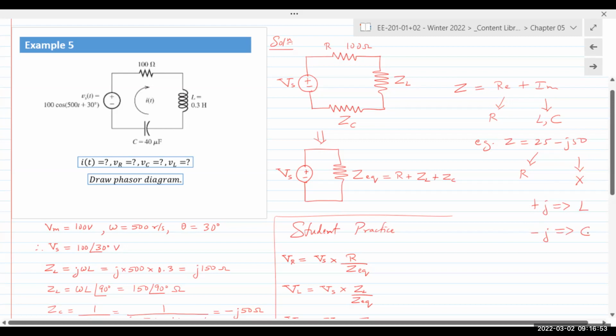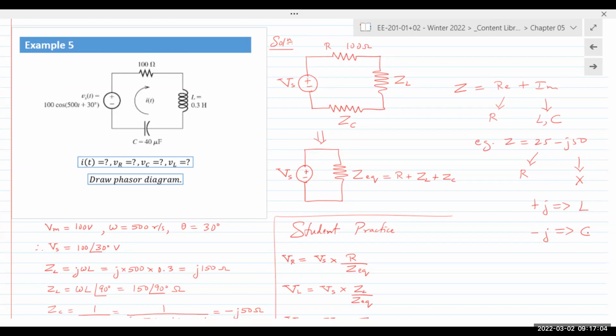Now, of course, if we have an inductor and a capacitor in a circuit, then you could combine that impedance and the result would be either a plus or a minus. So there would be no way to predict what kind of components comprise this total reactance. This assumes that there is only one component in there. Okay, and again, that depends on the problem, right? If the problem specifies that there is one single load, then you can safely assume there's only one capacitor in there.